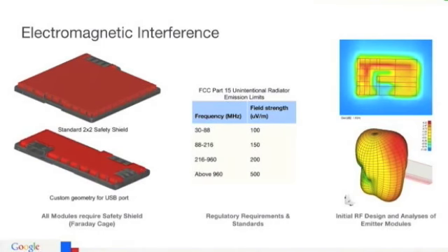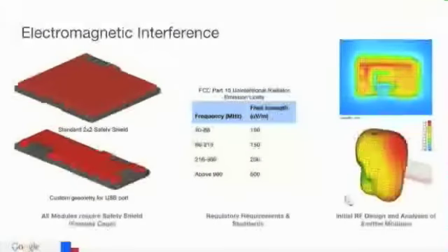So when we talk about EMI, we are concerned about radiative coupling, and to an extent, regulatory requirements provide us a convenient baseline to use for our own requirements. But we really have to look beyond these radiative coupling limits because we have modules that are operating very, very close together, centimeters apart, right?